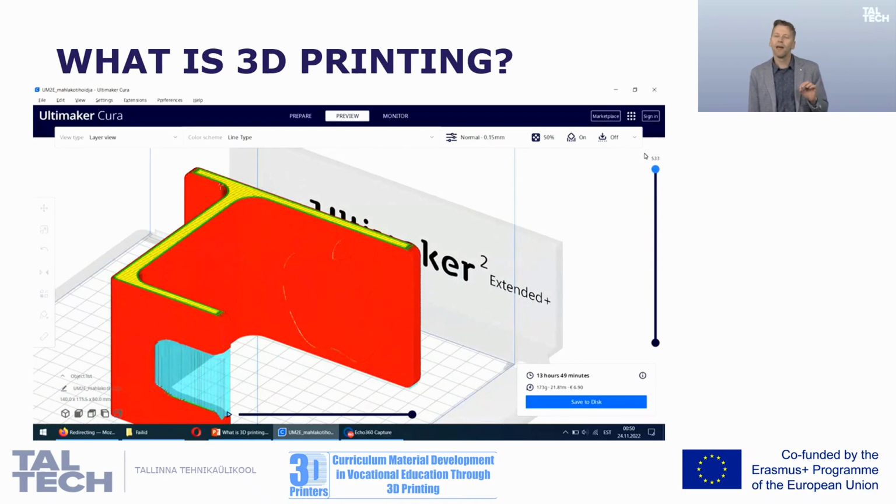Depending on the geometry, we might need to add these support structures that will hold the upper structures connected with the lower structures. Afterwards, we might need to remove these supports. Depending on the technology, sometimes it is complicated to generate and afterwards remove these supports. In some cases it is very easy, and in some cases it's not even needed to use supports.